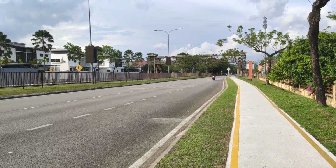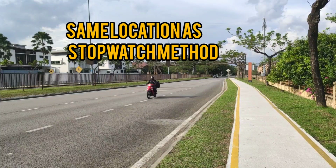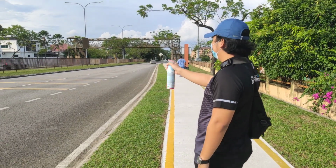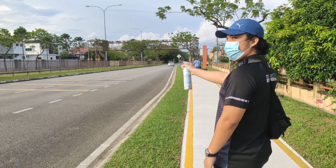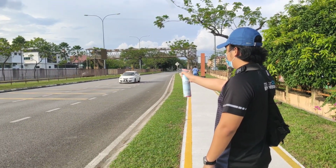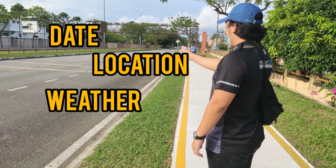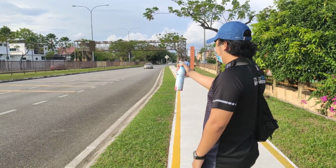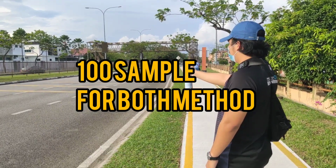Radar gun method. A location for placement of the radar meter was located. The positioning of the radar unit was determined, where the effective range may be up to 2 miles. The radar gun was aimed at a 30-degree angle towards the target vehicles. On the radar meter spot speed data form, the observer should record the date, location, weather condition, and speed of the vehicles. At least 100 unit samples were observed and data recorded.